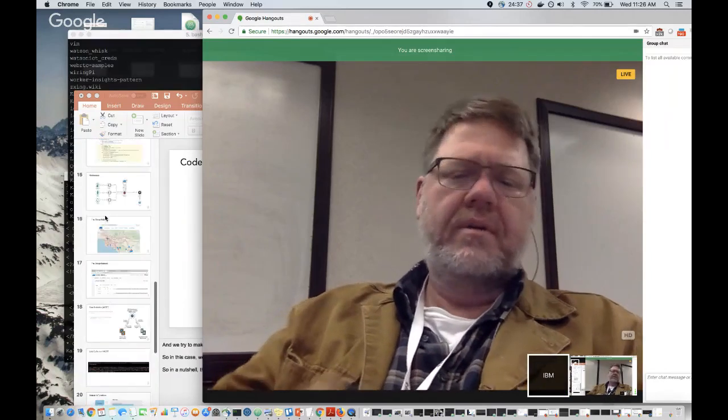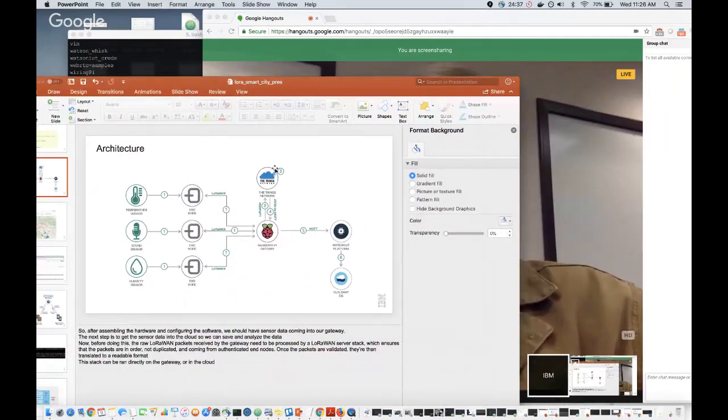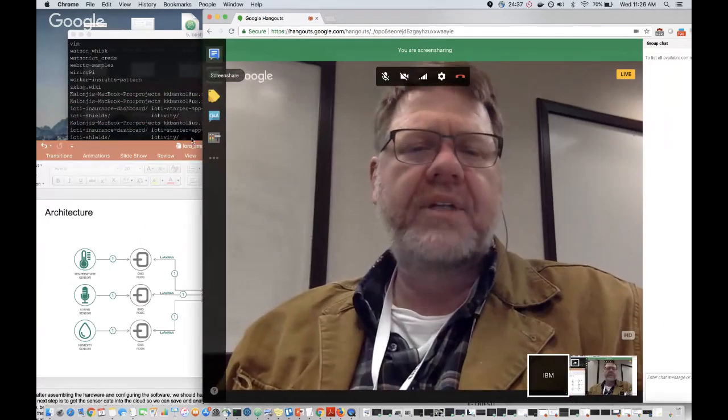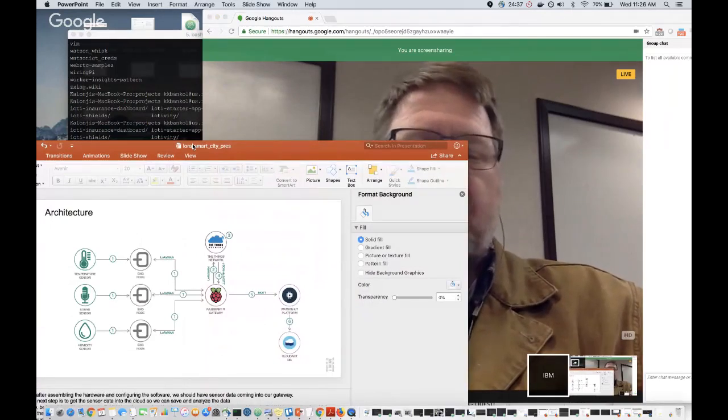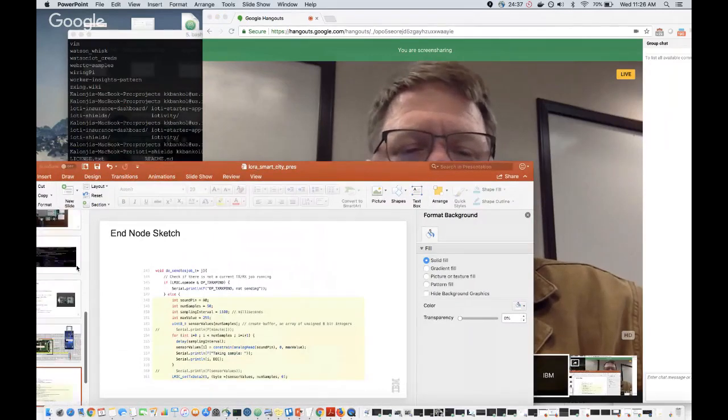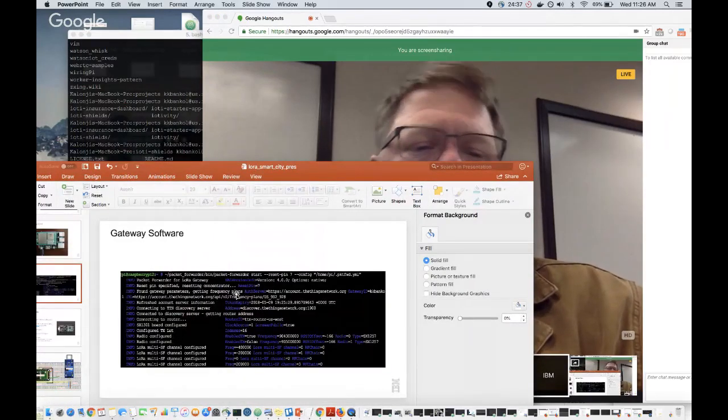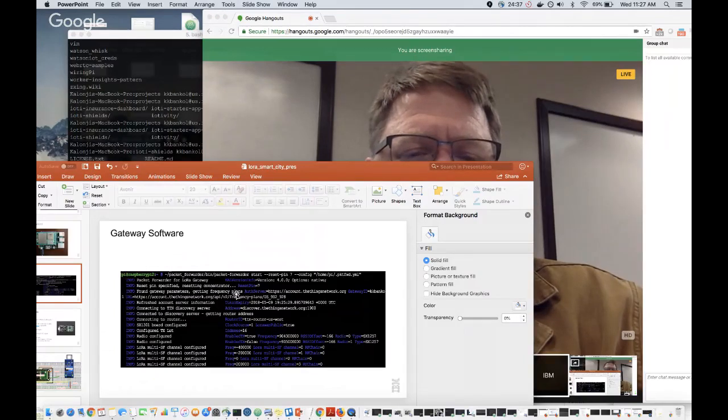That's actually handled by the LoRaWAN server. That would all be handled by The Things Network in this case, and once that's processed, The Things Network just sends you back your data as it was sent out originally. But you have to write the code that plugs into that server to do that unpacking, right? Oh no. Essentially, this packet forwarder service just sits and listens for incoming LoRaWAN packets, and as soon as they're received, they're sent up to The Things Network or whichever LoRaWAN server you might be using, and that's where the packets are rearranged and decrypted and so on.